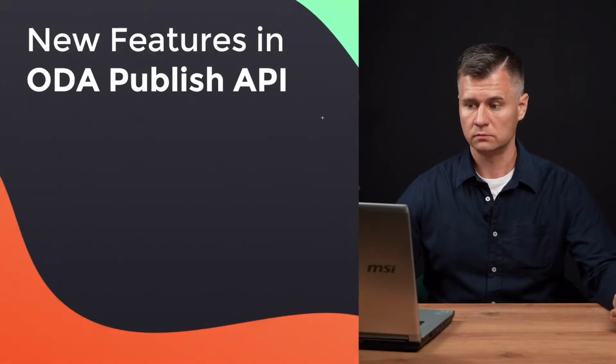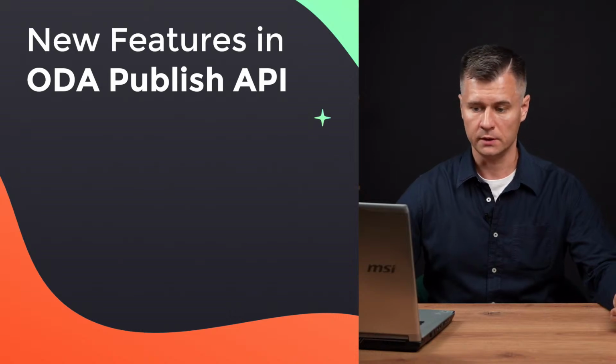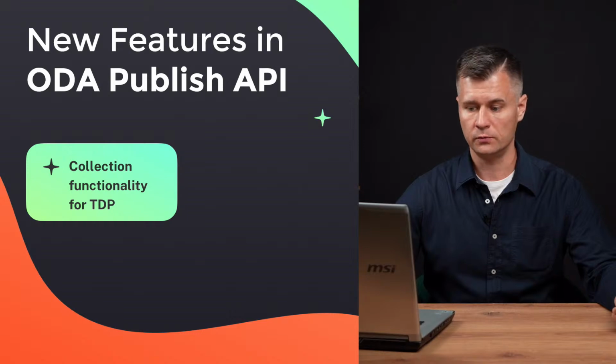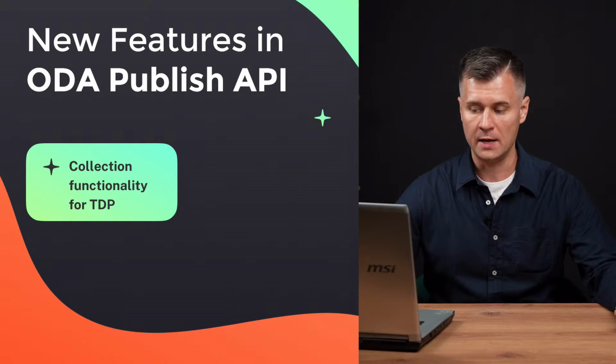And now new features in the Publish API, the next block of features. We implemented a bunch of new features. So first we implemented a collection functionality for Publish API. Simply speaking, we enabled the support for creating document collections, and a collection allows you to create a technical data package which allows you to combine in one document a set of different 2D and 3D documents describing the product. It is necessary, for example, to comply with the MIL-STD